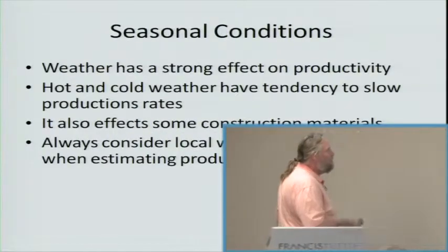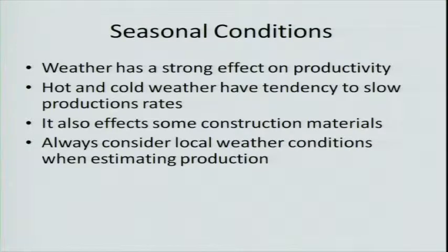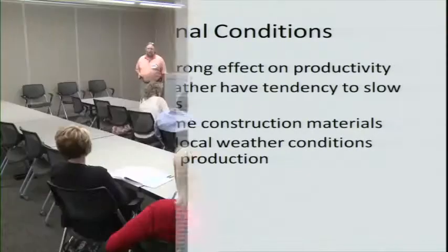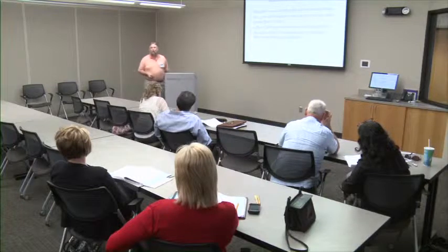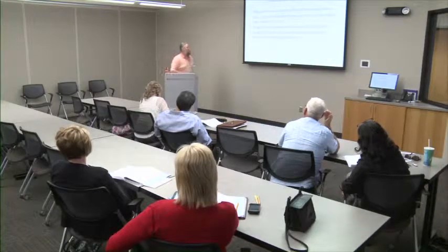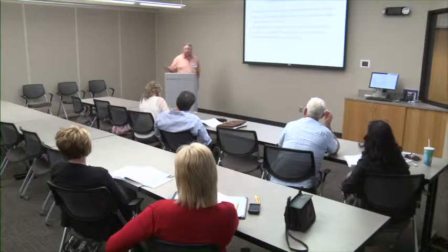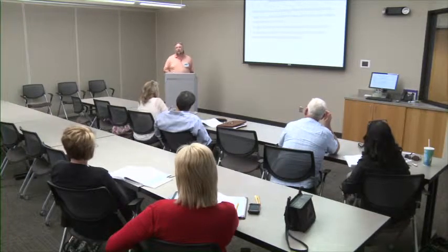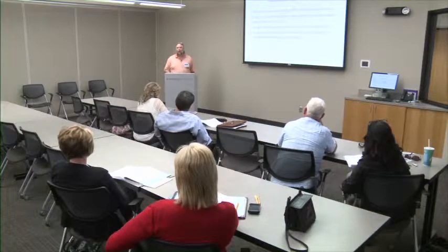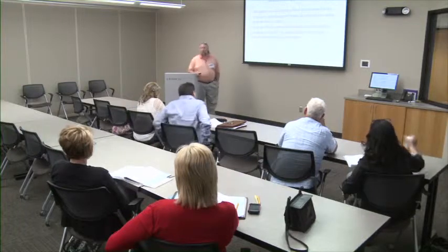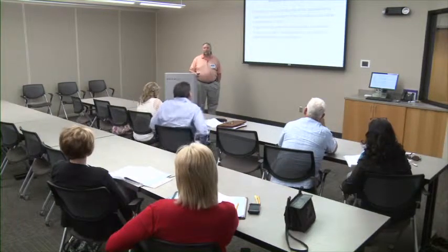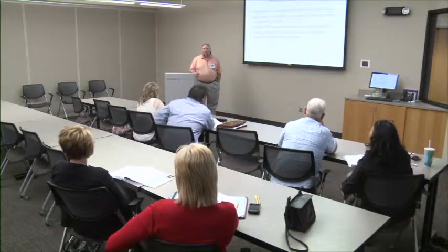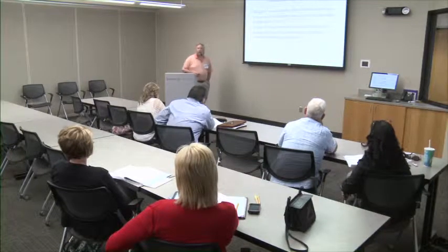The seasonal conditions: there's not a whole lot we can do about weather. We don't control that. I know my connections with the Almighty are not good enough to ever change the weather, and I don't think anybody else's are. So we just have to work with it. You deal with the fact that on hot days your production is going to go down, and on cold days your production is going to go down, and hopefully you get to work. You can adjust some of that. You see a lot of concrete poured on 100-degree heat days here. They start at 2 o'clock in the morning. So we make adjustments to compensate for what we have to do.